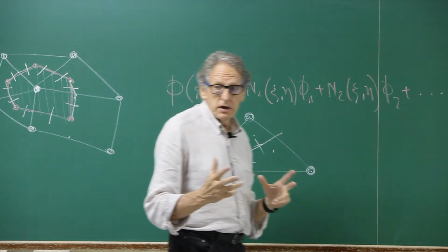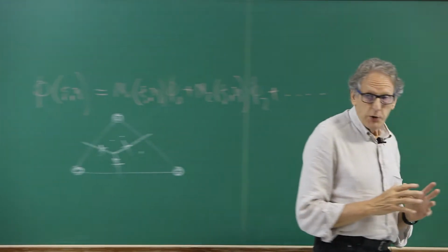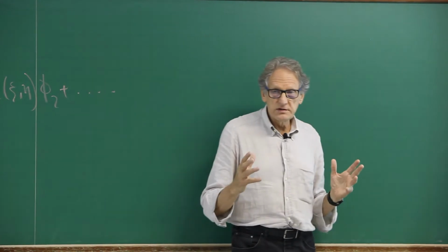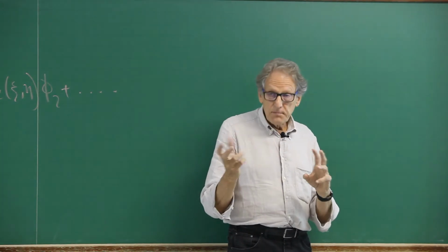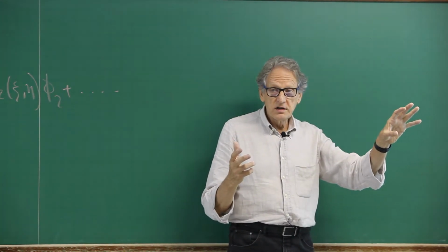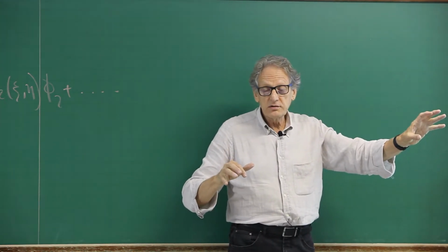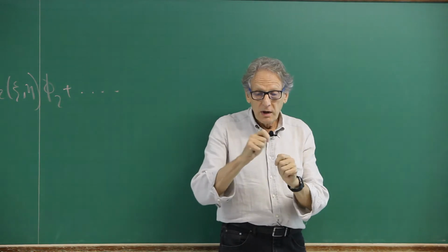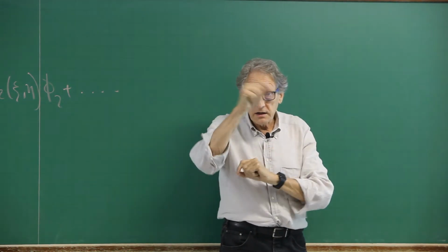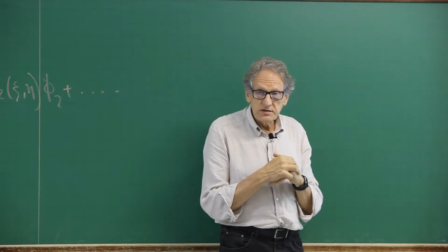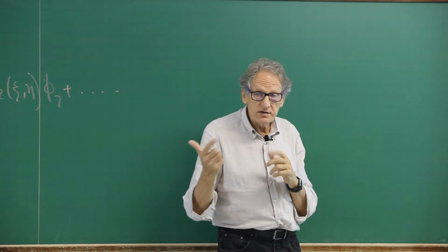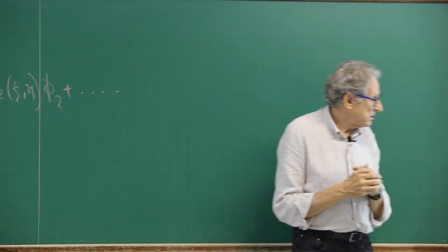So there is no need for gradient reconstruction. This is, let's say, the main difference between cell center and cell vertex. Cell center, you need a gradient reconstruction. Cell vertex, you calculate the gradients directly using the values on the vertices of the element.